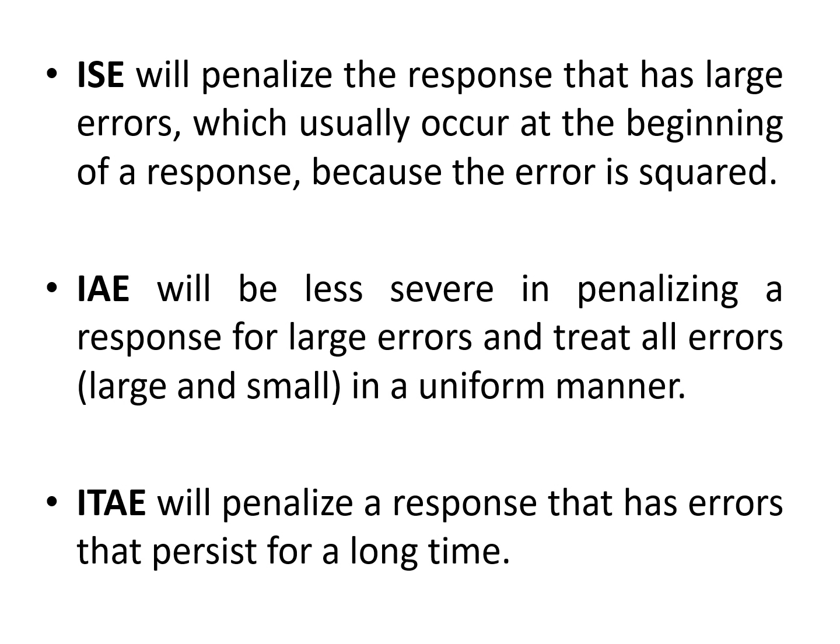You have to be careful about what sort of criteria you use. But for those other cases, with small errors and big errors, you can use IAE. It will be less severe in penalizing a response for large errors and treats all errors in a uniform manner. So in other cases where you do not have too-small errors, you can use the IAE method.